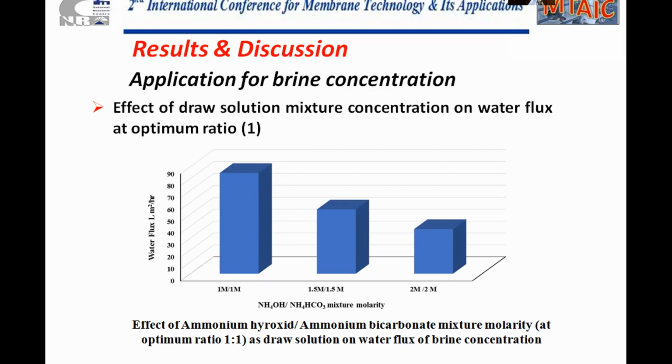The first is the high concentration of ammonia, which affects the membrane performance, and also internal concentration polarization, as we said before. This internal concentration polarization makes a boundary layer of salts around the membrane, hinders the water flow through the membrane, and declines the flux.